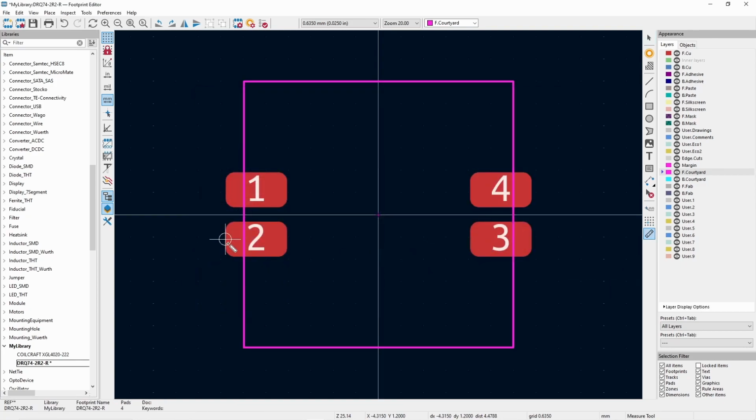And if we measure the distance between the two pads, we should get 7.9. We didn't, because I took the wrong dimension. So the X direction is 1.73 rather than 1. So what I need to do is minus 1.73 from 7.9.